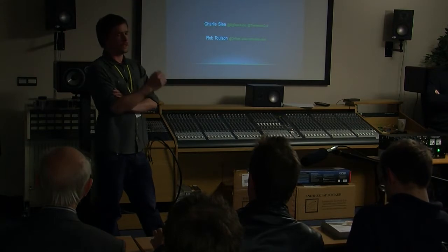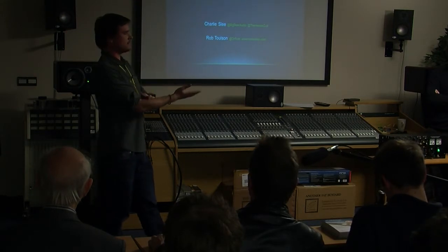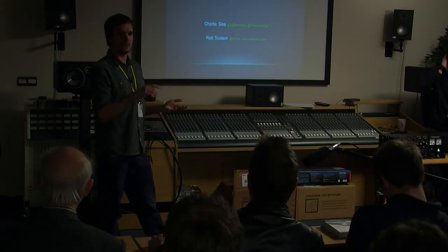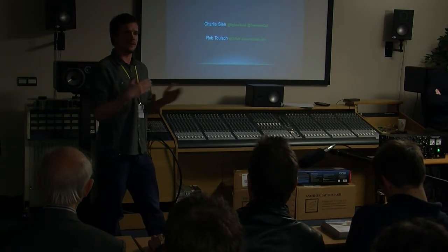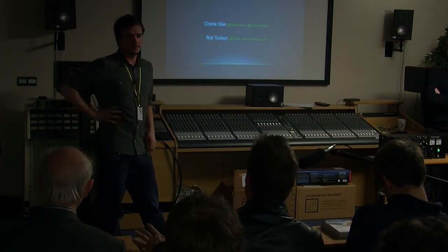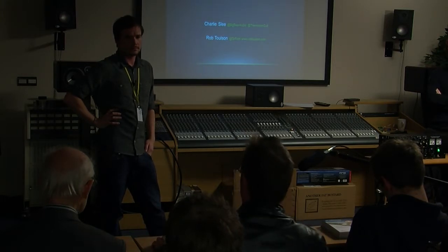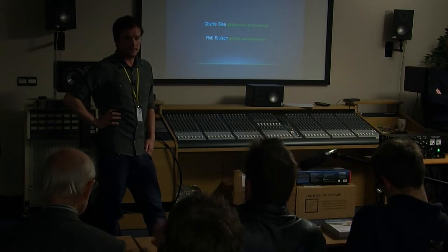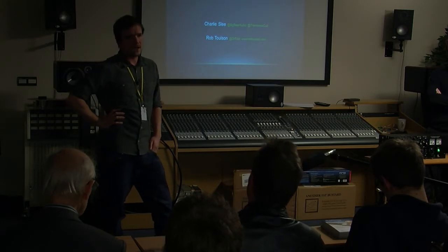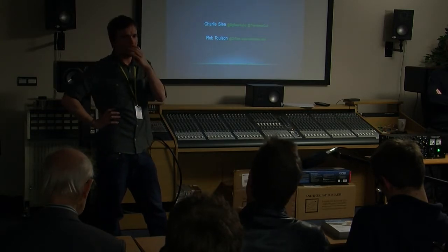It's absolutely still dominated by second and third, and that is the sound of the Phoenix. It's not just second; there is some third in it. I know that's the valve sound, and certainly I build guitar amplifiers for fun, and it's important to get that. But in studio gear, you want that distortion quite a lot lower.